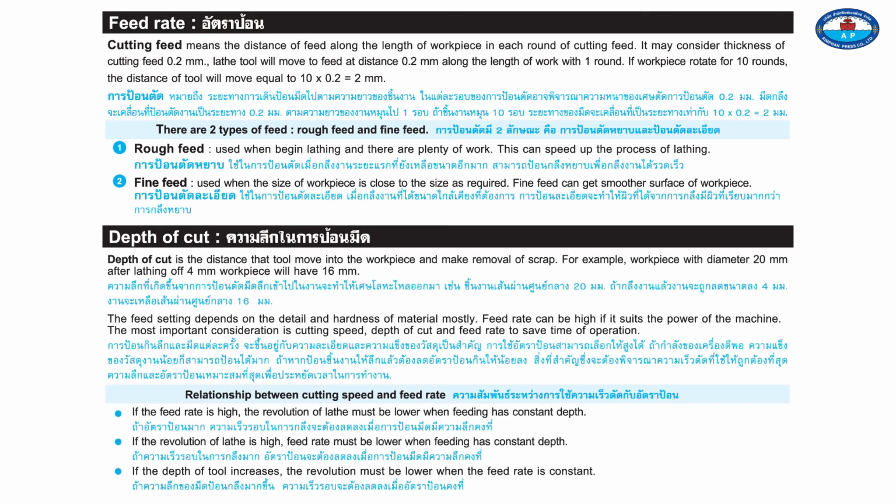Depth of cut. Depth of cut is the distance that the tool moves into the workpiece and makes removal of scrap. For example, a workpiece with diameter 20 millimeters, after lathing off 4 millimeters, will have 16 millimeters.